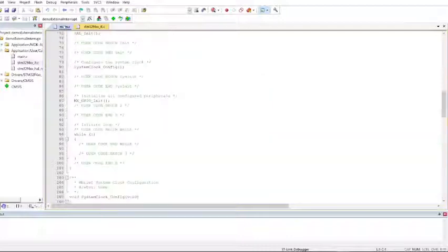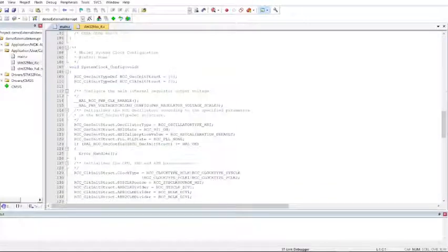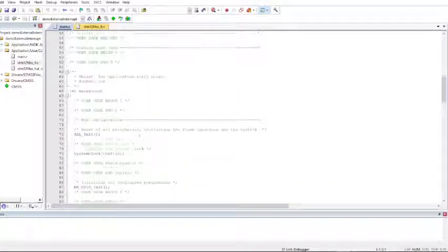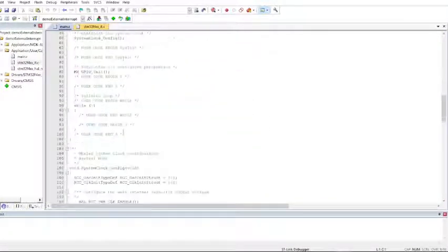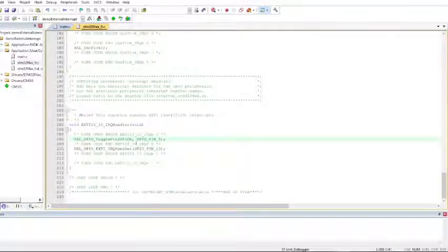I hope you already know the concept of interrupts. It's basically allowing your main program to do freely what it's doing until such cases where, let's say in our mode, a falling edge trigger is detected in our interrupt pin.